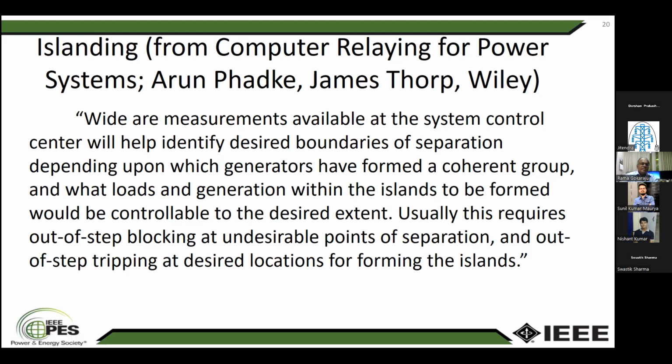One thing to note here is we are not going to trip wherever possible on the lines. In some regions, out-of-step tripping may not be desirable. So in those regions, we are going to implement the blocking function, even though it may take a larger portion of the system out. And in some portions, we'll do an out-of-step tripping at desired locations to form the islands.